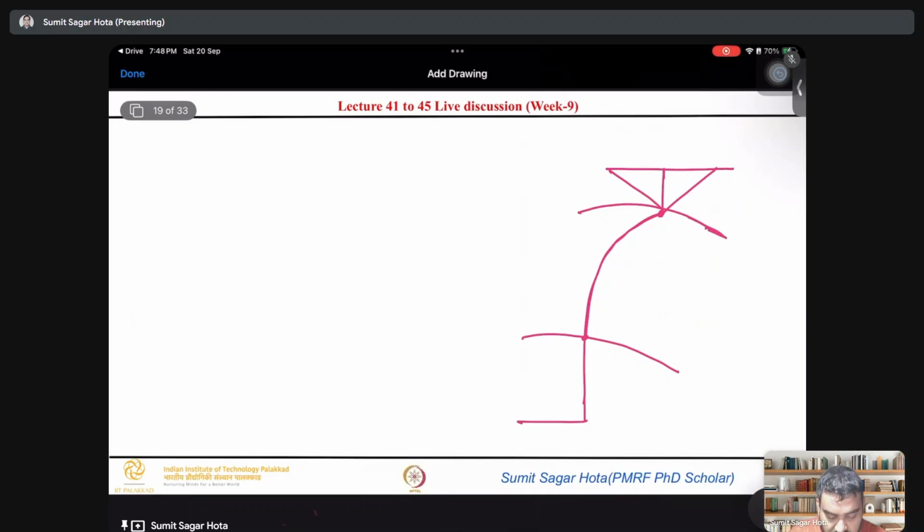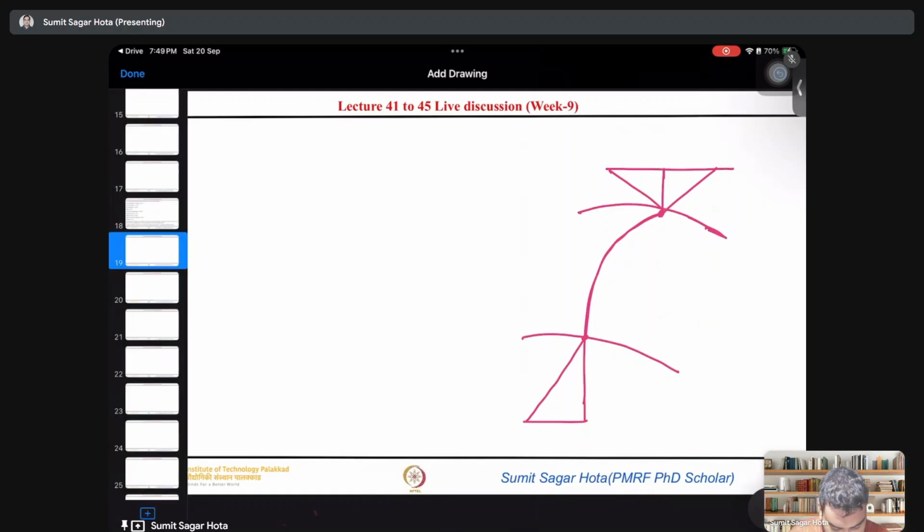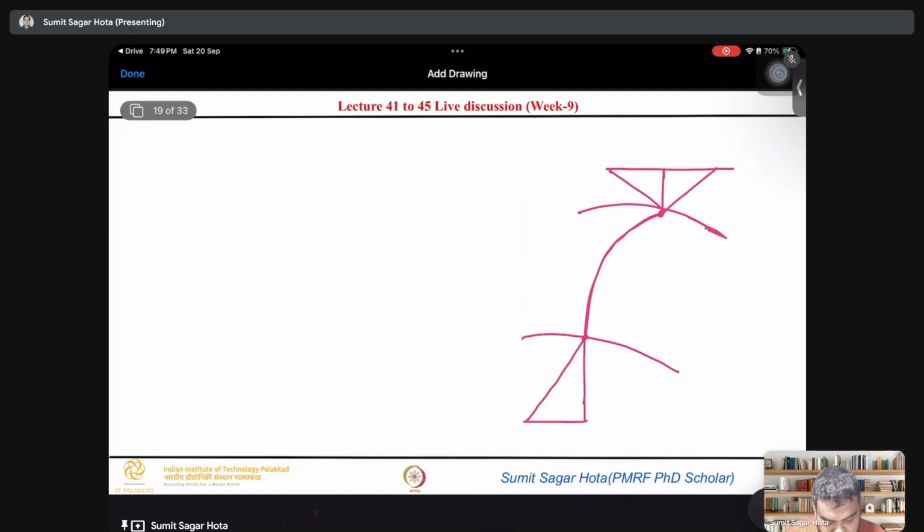Okay, I think you solved the question. Now just see how I am solving this question. So first of all, we should do the velocity triangle. Because for these types of questions, especially the centrifugal compressors, we need the velocity triangle first.